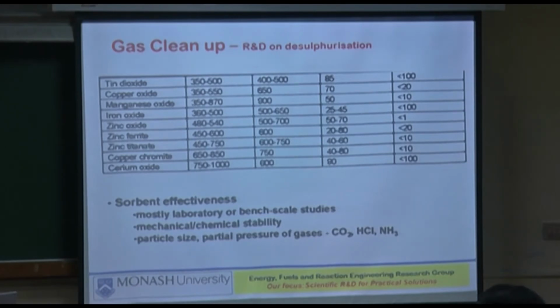Because if there is too much of a pressure drop, then you have other downstream problems. The gas pressure and the gas temperature will be dropping, and then you will have to overcome a few other issues. So pressure drop is one of the criteria. To answer your question, I think eventually you will have to decide between the size of the particle, cost of the particles, etc., and their easy availability for replacement. But either way, both zinc and iron oxides lend themselves quite well to regeneration.